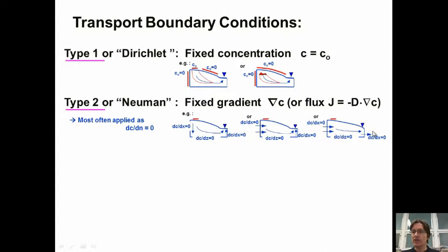And a third case here, we've got an outflow boundary. So here, a 0 concentration gradient also applies, even though there's flow across this. All we're saying here is that there's no dispersive mass flux across this boundary. But from the flow solution, the velocities here will give us an advective flux, so mass can still leave this boundary. So we see all these different contexts where a 0 gradient condition applies. It's quite general, and by default in most models, this is the condition that applies.